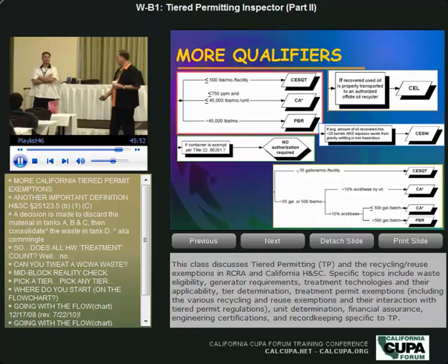Now, that may be an interpretation. The higher the amount, the higher the hazard, the more complicated the process, the higher the tier, right? If it's a flow-through treatment, it's not batch treatment. You could probably say, well, look, because we're not treating in batch, we're treating in flow-through, you can almost inherently interpret that they'd fall under less than 500 gallons per batch, because what they're treating is certainly less than 500 gallons. But that's an interpretation you may have to make for flow-through systems when the tier is based on batch.